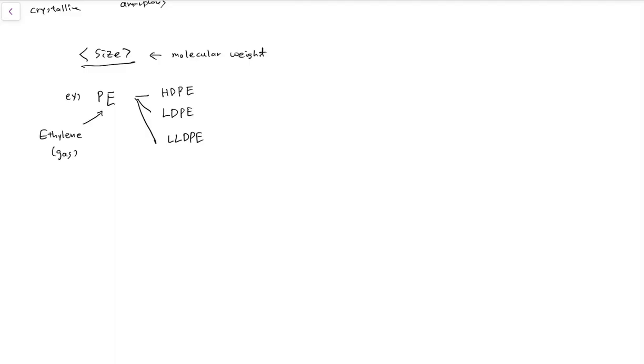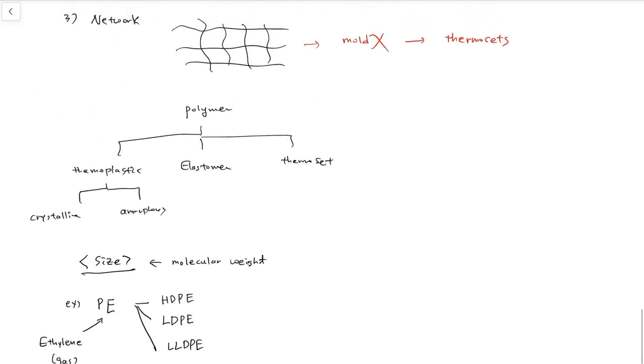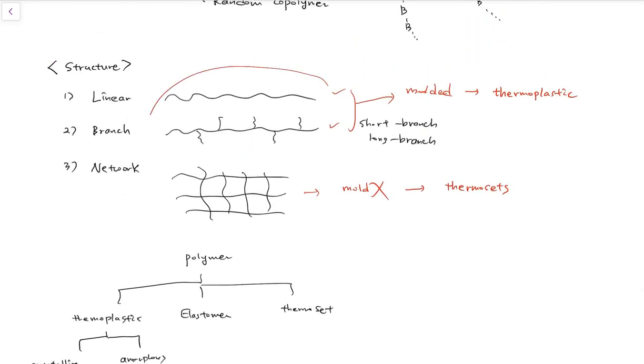We have already seen that the molecular structure of polymers determines the physical properties. So HDPE means high density polyethylene, so density is very large. If you go back to these structural properties, if the molecular structures of polymers are, for example, linear or short branched, you can imagine that the packing of polymer chains would be more efficient than, for example, long branched ones, right?